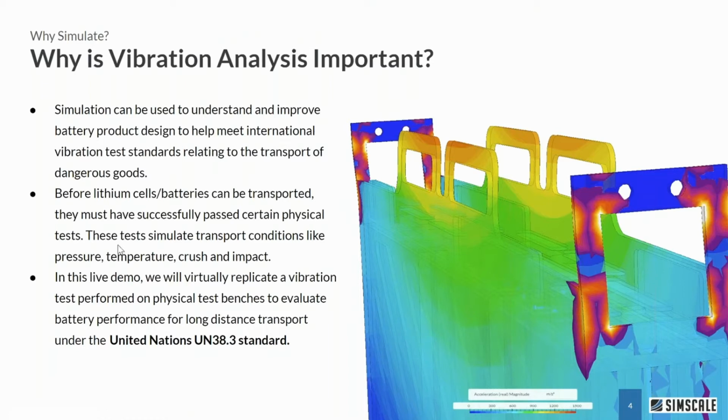Particularly for EV batteries, before lithium cell batteries can be transported, they must have passed certain physical tests. You can't escape physical tests, but these tests simulate the transportation conditions like pressure, temperature, vibration, crush, and impact.